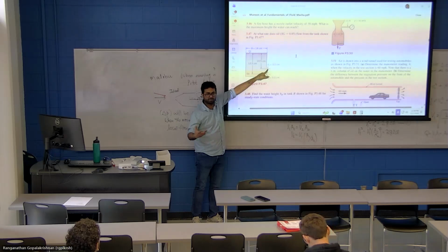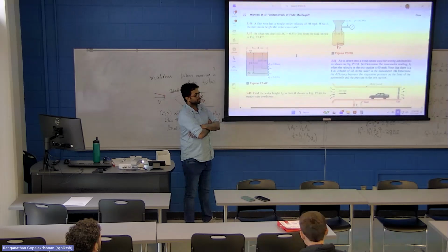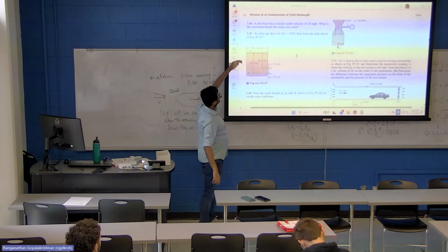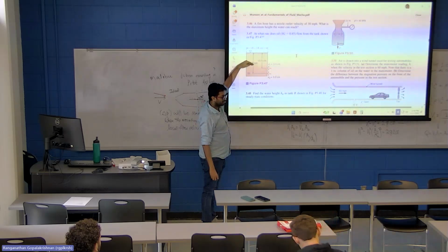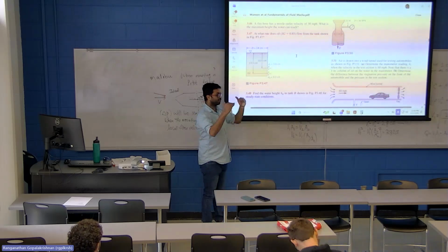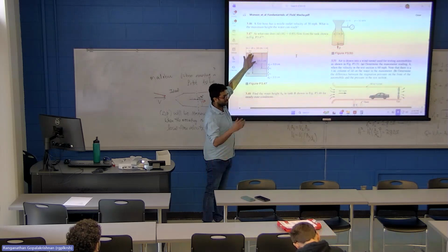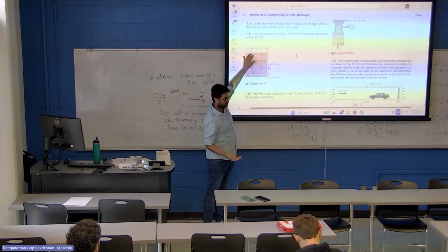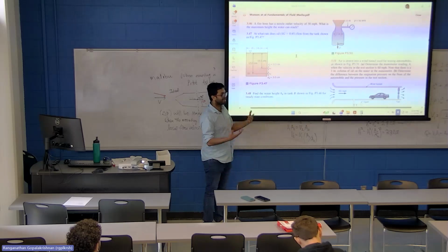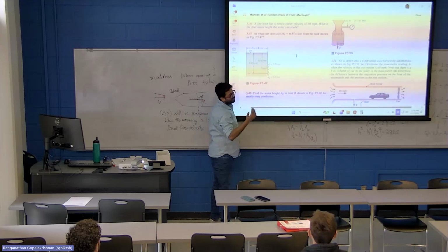Okay. Is that a question? Yes, would you do the point at the top all the way to the left or all the way to the right? Or like somewhere that doesn't matter? It technically doesn't matter because you know that pressure only depends on height. So if you think of the top surface, you consider the top surface to be at rest, in the sense it's moving very slowly compared to the exit, that whatever fluid velocity is over here, we effectively consider that to be zero. So it's static fluid at the top. So any point that is at the same level is at the same pressure. So the choice of whether the point is labeled here or here at the center, it's not important.